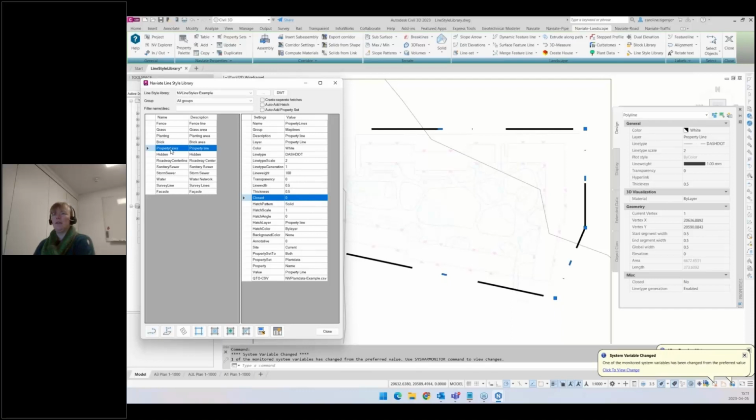And depending on the line that you're using here, you can see different information. The file line style example is actually intended to show you the options that you have here. Usually this will probably be a lot of by layer. And I'll come back to what that means, but I just want to show you the command first. So until closed, and closed is an important thing to remember, because if I have that as a 0, it means that the line won't be automatically closed. But I can set this to 1.